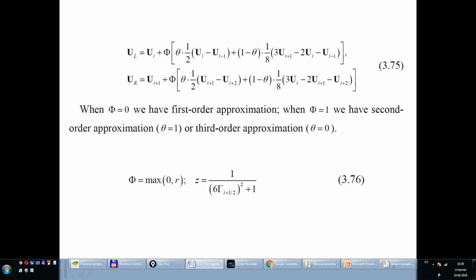The simple extrapolation formula assumes a smooth variation of vector U. However, discontinuities in U are possible, that is, shocks. There is a need for some mechanism to sense such discontinuities and limit the variation of U in these extrapolation formulas.